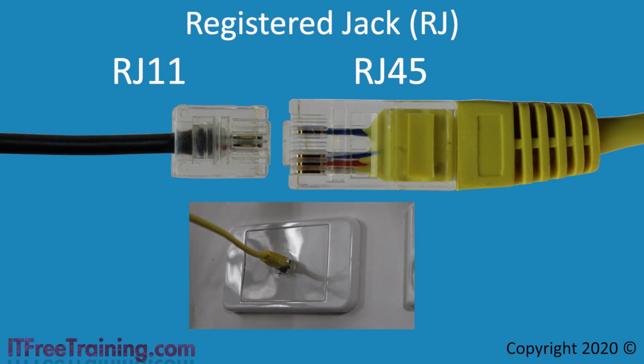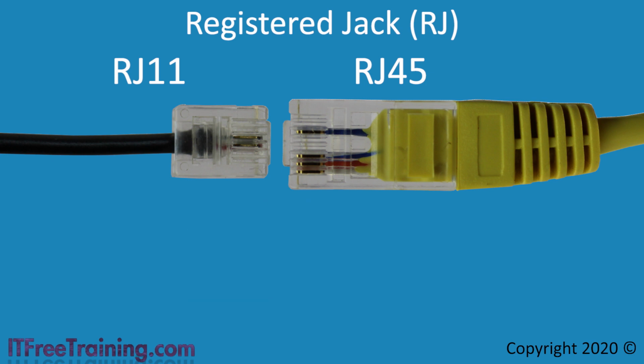Both connectors will work in the same plug without issue. You will find that older telephones will use the RJ11 connector. These will be plugged into RJ45 network sockets and run over RJ45 cables back to the network cabinet. Since the RJ11 pairs are separate from the 2 pairs for networking, this will not cause any problems.